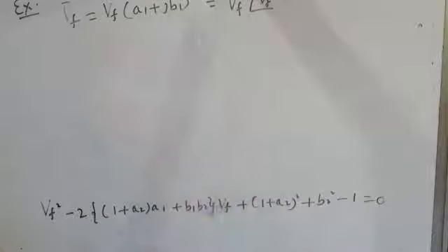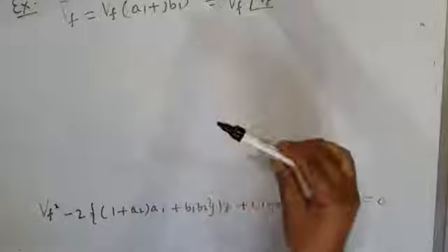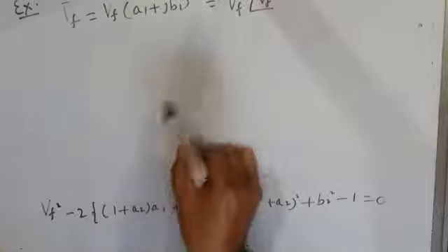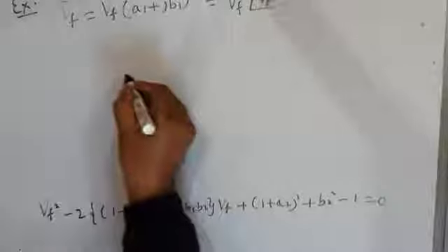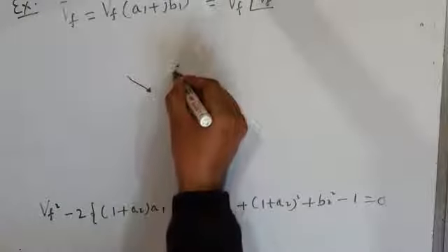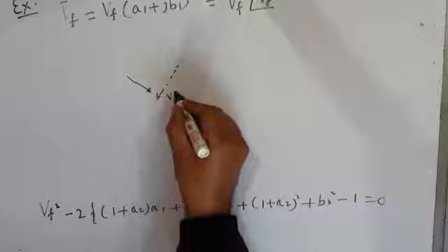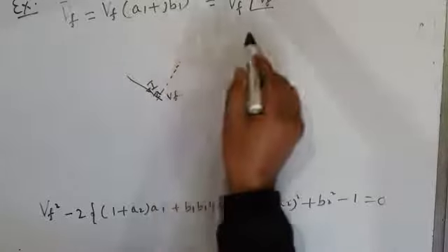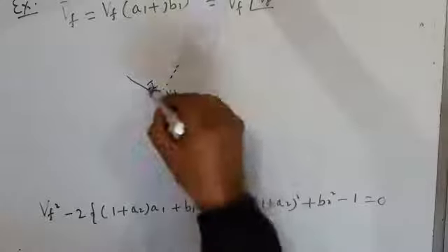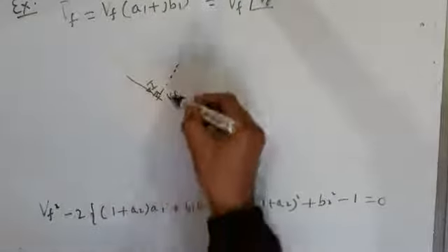The load voltage is the same as the source voltage, in this case 1 per unit. And that injected voltage, as you have seen from phasor diagrams a few moments back, is in quadrature with the current. That means if your load current is this, the injected voltage will be at 90 degrees, so that the DVR does not supply real power, it supplies only reactive power.